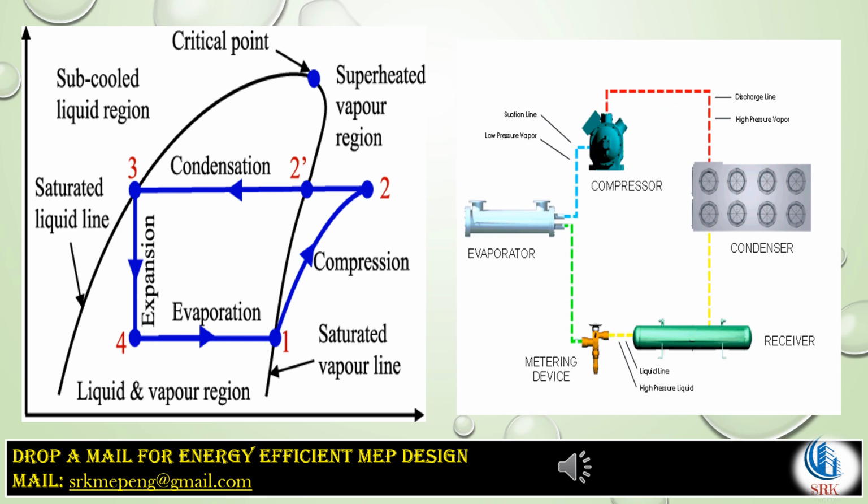Leaving aside the theoretical aspects, the refrigeration cycle comprises four main components. The compressor, as the driving mechanism, compresses vapor. It is crucial to understand that a compressor theoretically cannot pump liquid. It compresses refrigerant vapor into high-pressure, high-temperature vapor.